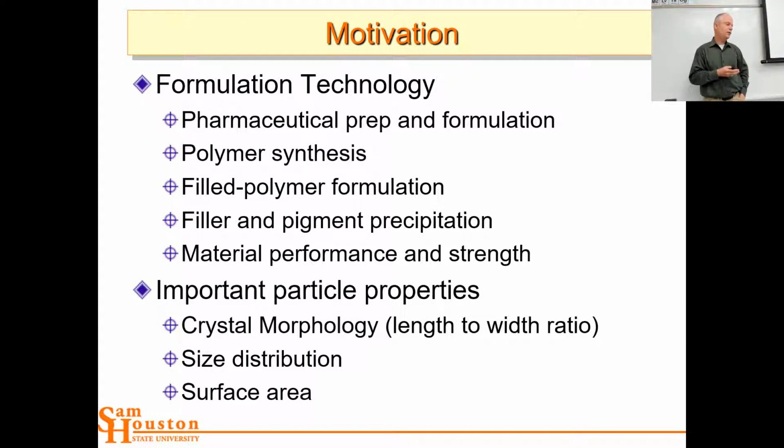Other things too, for polymer synthesis and filled polymer formulation, these kinds of properties can be important. And I wanted to see if we were able to see different crystal morphologies. So what's a crystal morphology? Plates, needles, gravel, what's the shape or the form, morphology, what's the form of that crystal? We'll get a certain size distribution and a certain surface area. Those are important parts. Also, crystal shape, like length to width ratios. And so these things come into play. And I think in Petrokovic, y'all do some particle counting and some particle size distributions. And so it's important in those areas.